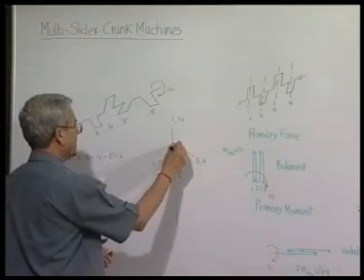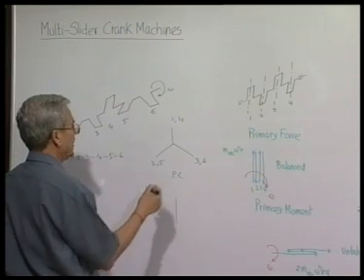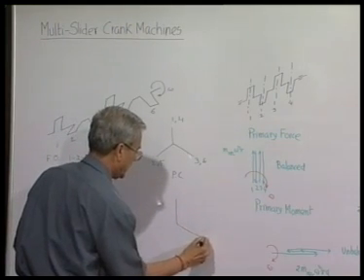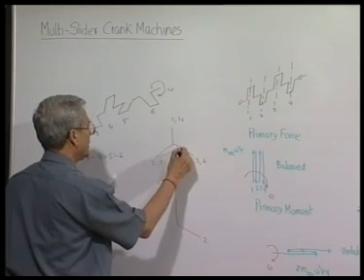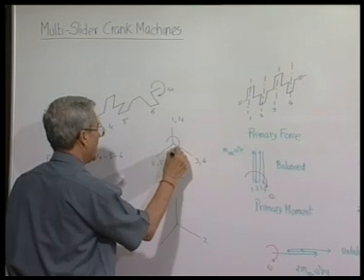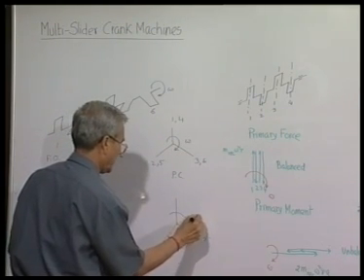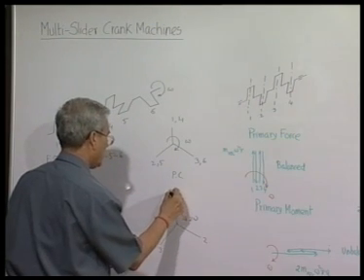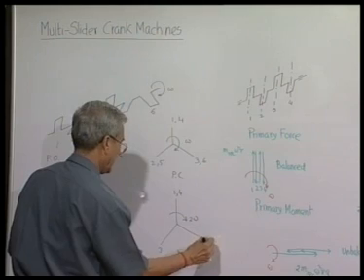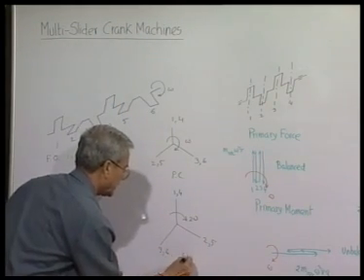For 2 the angle is 240 degrees, so double of that is 480, that means 360 plus 120. So, 2 will be here, then 3 is 120, double of that is 240, so it will go in the direction of rotation. 3 will be here, 4 will be again here, then 5 will be here and 6 will be here. So, this will be the secondary crank.